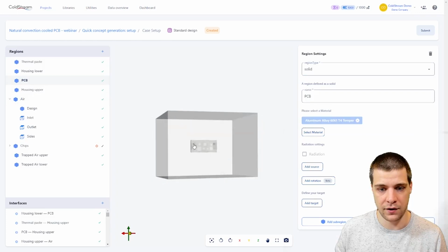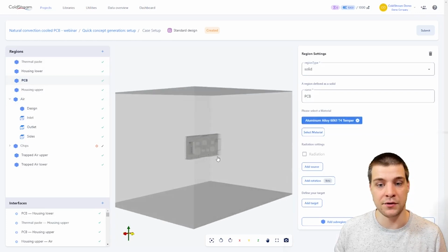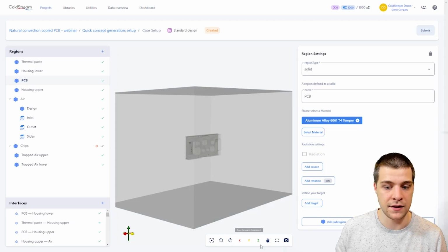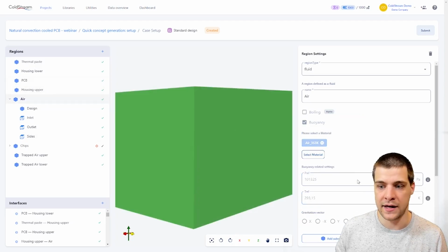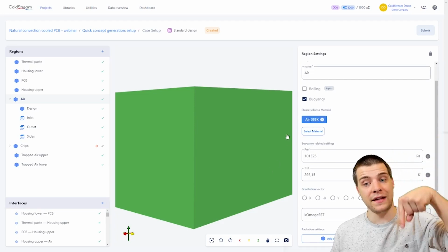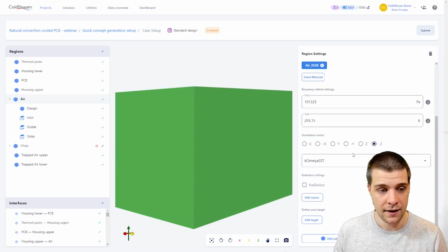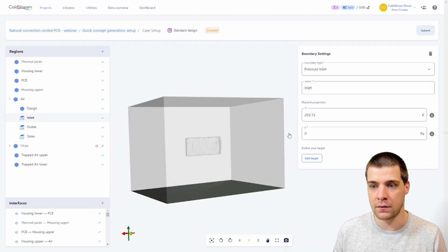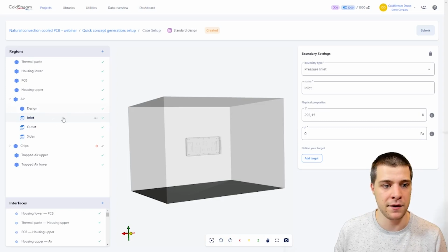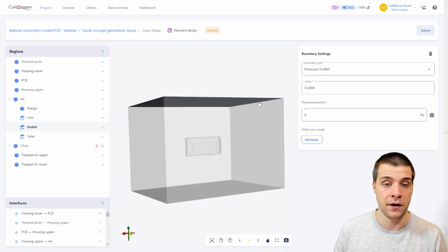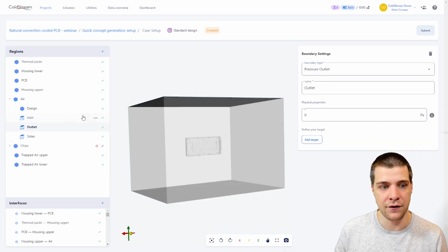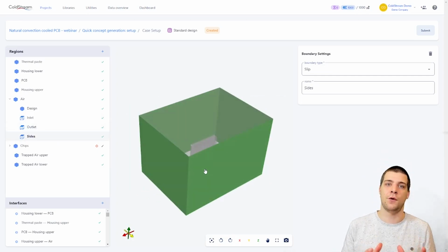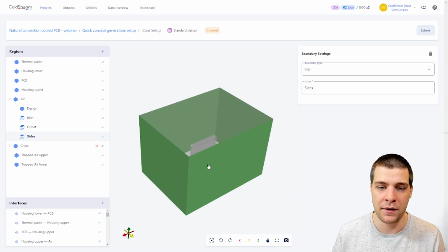So if we have a look like this, this is the correct positioning of our PCB. So the green arrow represents the z-axis, and here we specify the gravitational vector being pointing downwards. Alright, and then we allow an opening on the bottom with again environmental temperature conditions, and an opening to the top where the molecules can leave, and then on the sides we will assume that this is a repeating geometry.